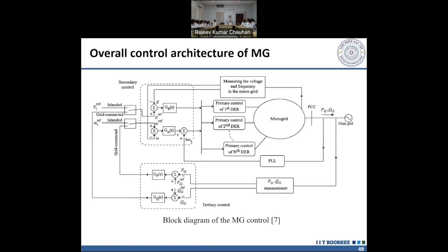Your voltage will fall down to, let's say, 215 or 220. At this moment, you will set the frequency to 50 hertz. Means you have to bring the speed up to that level so the frequency is 50 hertz. Means your prime mover is also supplying the 250 kilowatt.